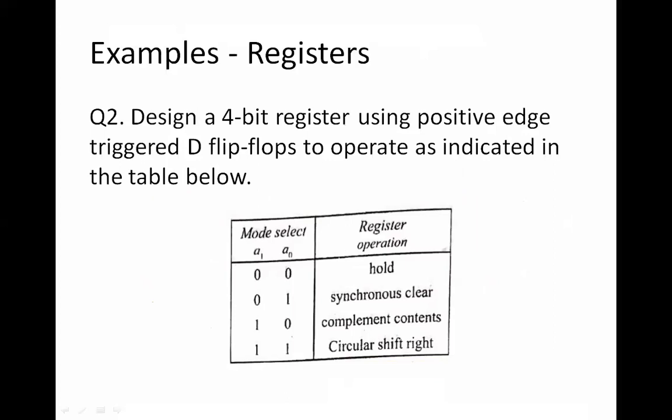What's the difference? In shift right, once we move the bits to the right-hand side, the leftmost bit is not considered anymore. In circular shift, the last bit comes and takes the place that is otherwise occupied by zeros. In a normal shift, the leftmost bits will be occupied by zeros.